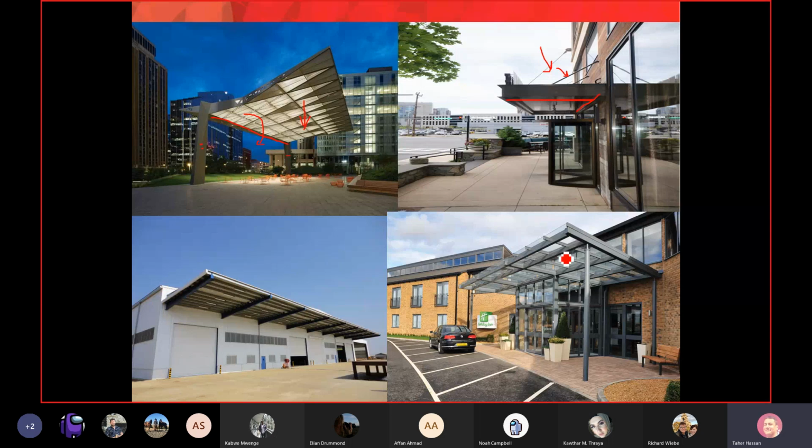Now let's do the last exercise. Not the last, we still have two. The bottom right picture. Do you think this beam close to the building, which is not very clear from here, but there is a beam over there, would have any torsion? No. Because those columns are holding the canopy up, and that's why this beam doesn't have any torsion.